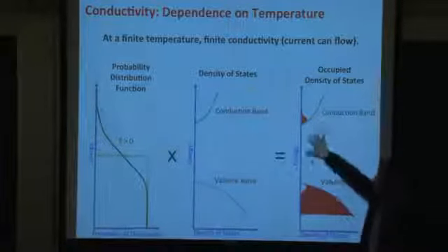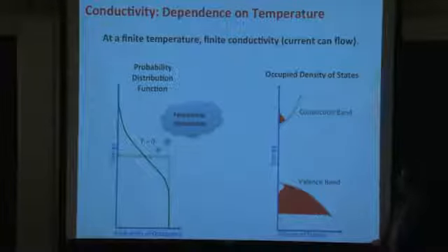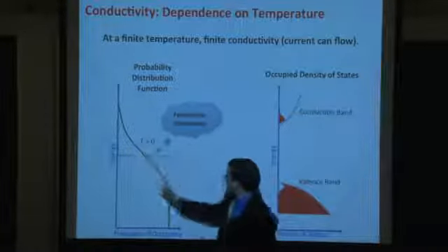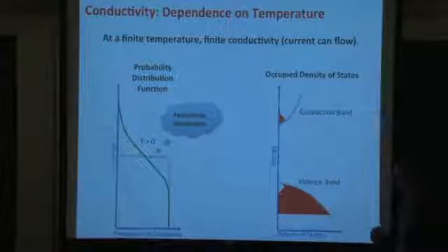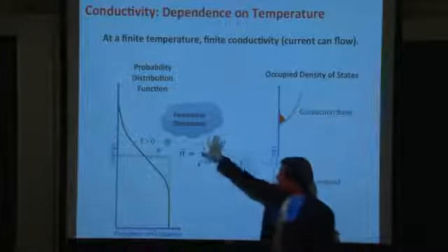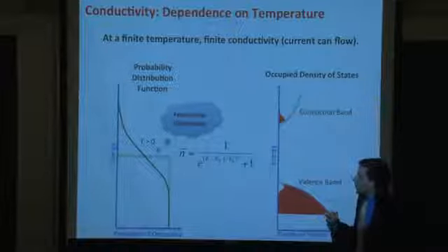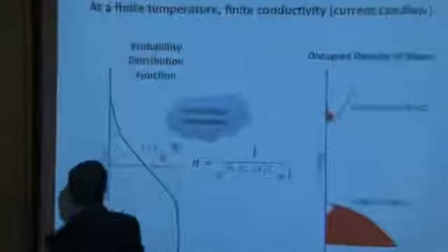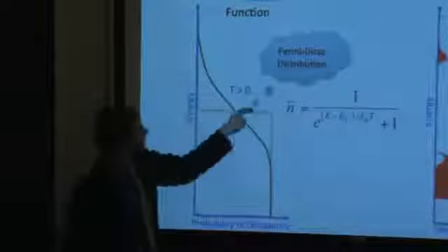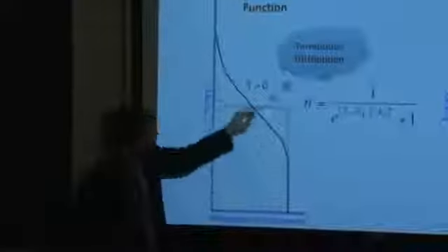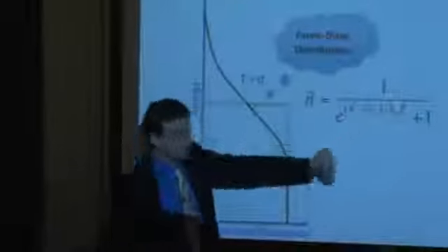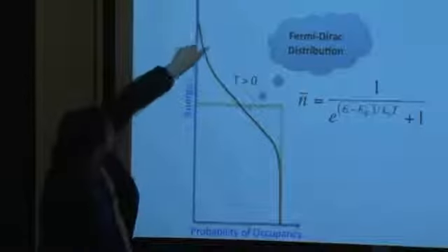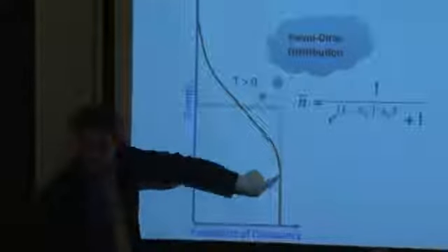So what can we do with this framework, with this understanding? Well, we can look at this function here and ask ourselves, what is the name of that function? It's called the Fermi-Dirac distribution, and it's given by this equation right here. We'll notice that this equation approximates to an exponential as we move further and further away from the Fermi energy, the Fermi energy being defined as this energy right here. If we move further down here or further up here, this starts looking an awful lot like an exponential, meaning this right here and this right here start looking like exponential functions.